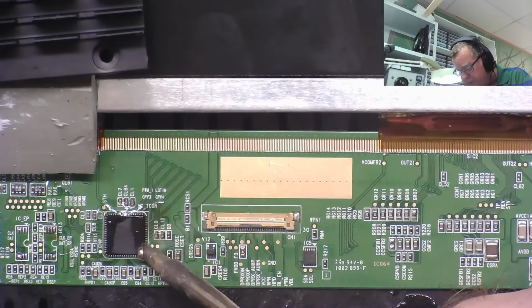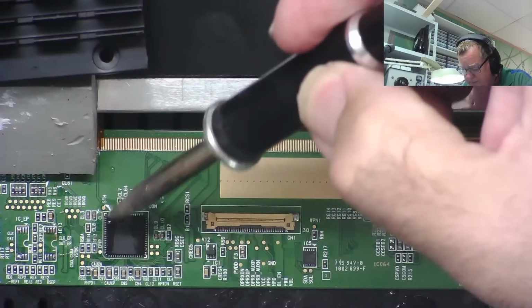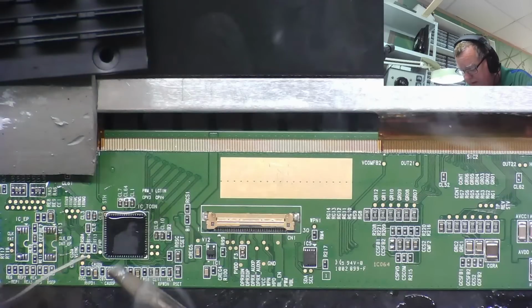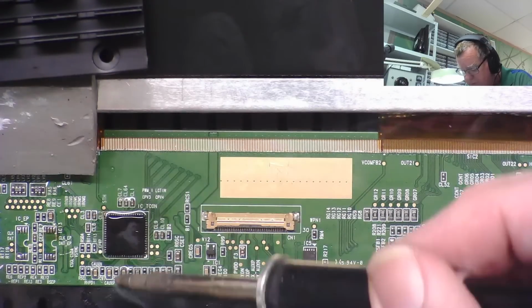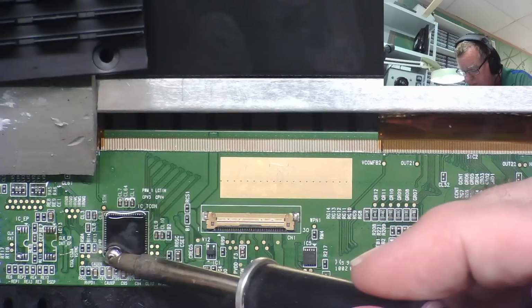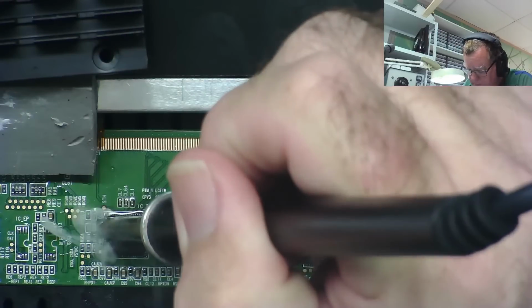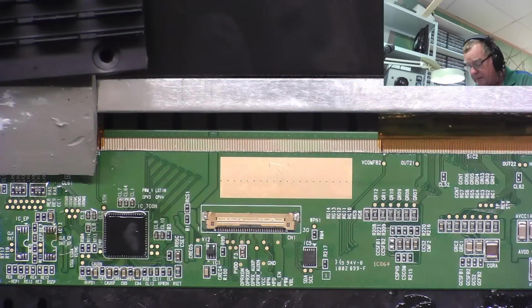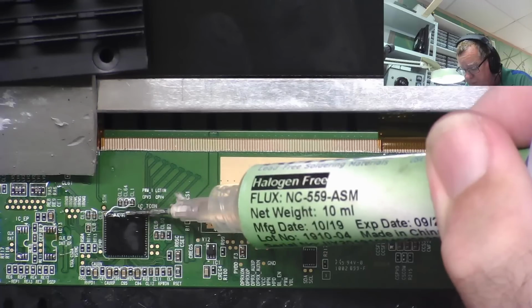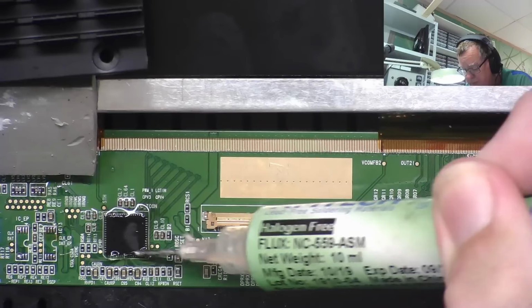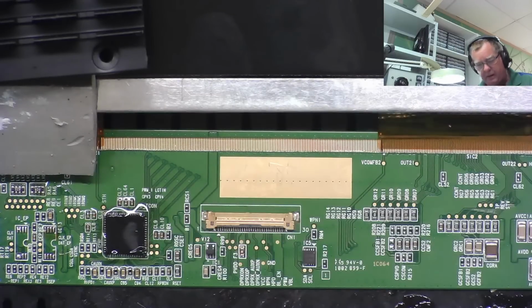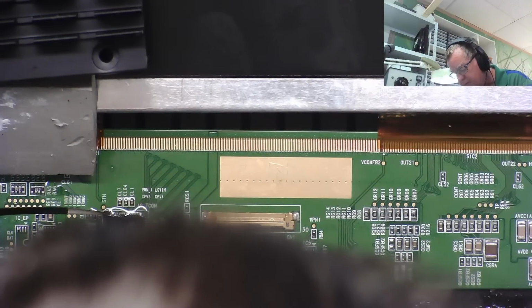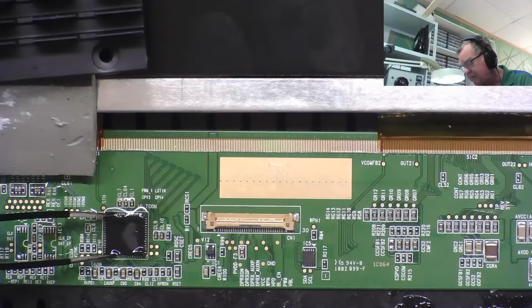But to be quite honest, because this thing has a large pad directly underneath it, almost the size of the chip, this probably isn't going to have any effect at all. But anyway, we can see. So there's a blob of solder on the end of the iron. That's as best I can do. So hopefully a little bit more flux. The flux is going to run underneath this and maybe help to desolder it. And I'm going to try this time to pick it up without the Kapton tape. So this will either work much better or make a right pig's ear of it.